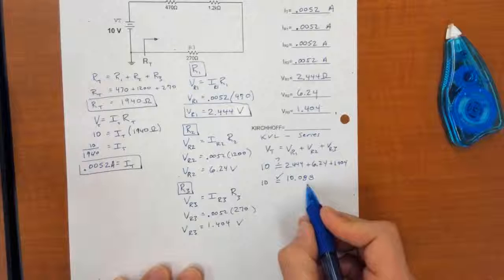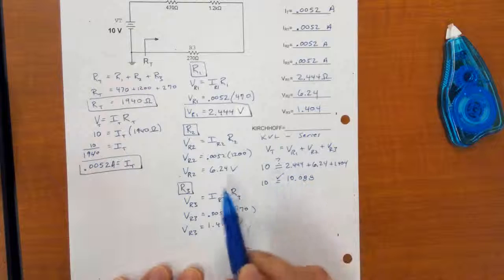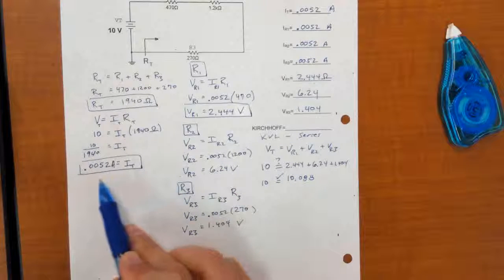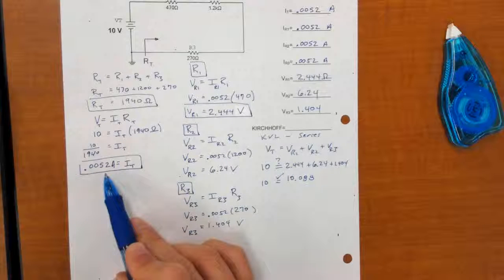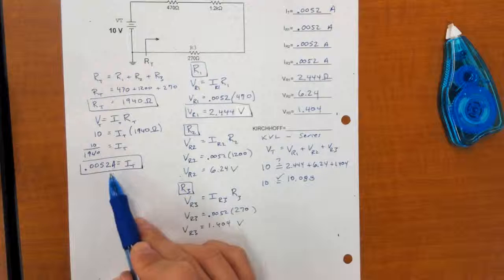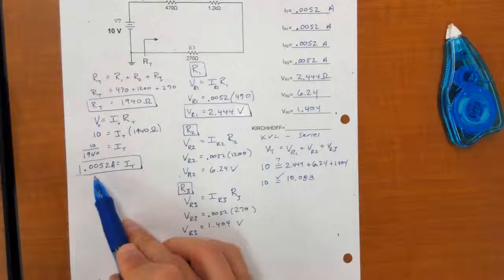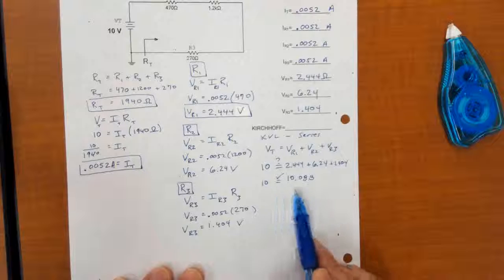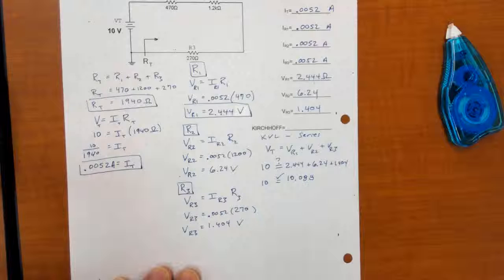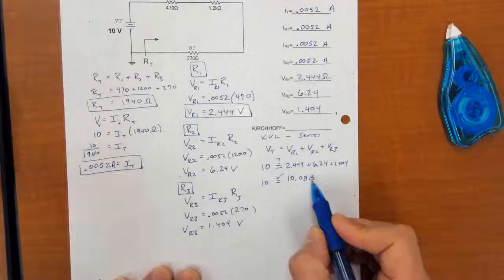Why am I off by a little bit? Well, when I went through and found all these voltages, remember that I used this 0.0052 current. That was rounded. That was a decimal that would fill up the entire screen of my calculator. And so it was just something that we needed to round at some point. Had I taken it out many more decimals and done my calculations, I probably would have gotten this to be closer to being exactly 10, but maybe still off a little bit, as what was on my calculator itself is probably a rounded value. So we will say that Kirchhoff's law is confirmed.